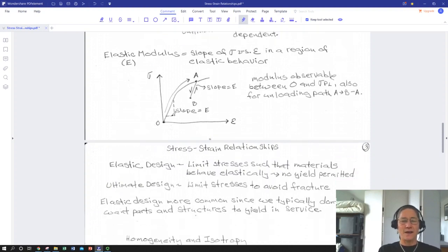Okay, let's see, we've covered this. Modulus, elastic modulus, big elastic property. We're going to see this a lot. It's the foundation for Hooke's law, along with Poisson's ratio, which we'll get to next. And remember that it's the slope we follow as we load a material and unload it. So anytime we start to load a material, or unload it, we instill or release that stretch elastically.